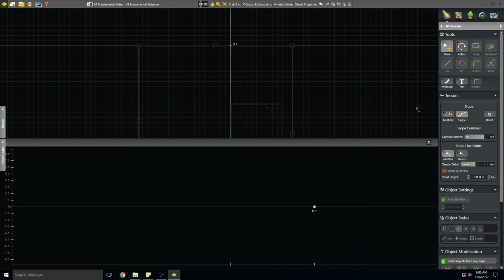We're going to go over to the panel menu, and in the slope line point section, down towards the bottom, you'll see a 0 feet, 0 inch value box there. Point height is what that value is. So the point height here is going to be 5 feet. That's the top of our slope, kind of like a short exaggerated slope or a berm. So I'm just going to left click on the up arrow and change 0 feet to 5 feet.